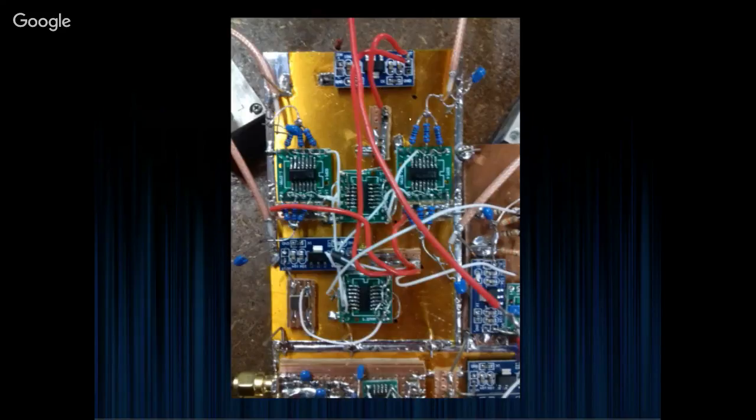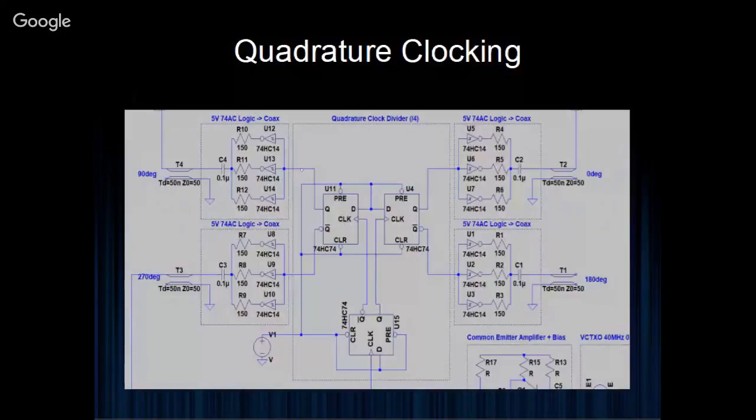And actually on a number of these, I've used a ferrite combined with a capacitor to try to minimize the EMC released, and also to try and keep a handle on how that propagates throughout the rest of the circuitry, because there are a couple of critical references which could be done a lot better, but when I had the time, I was doing it. So yeah, this is laid out more or less as this is, so I tried to keep them as similar as possible for ease of understanding.